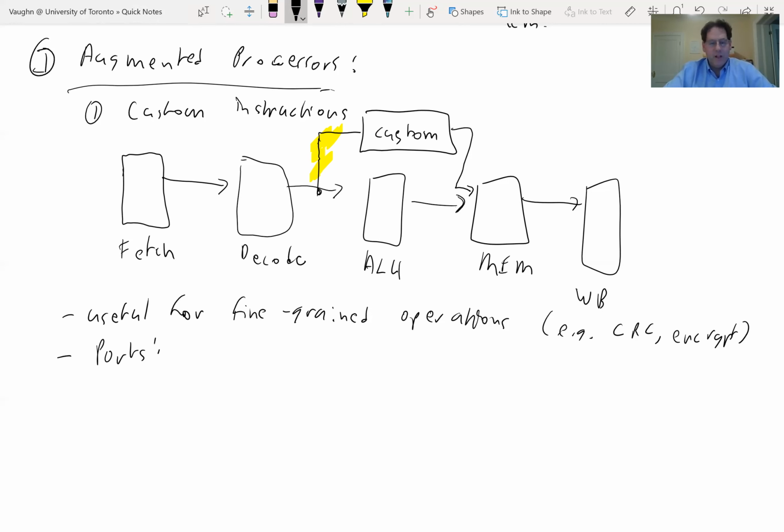The register file is centralized storage. It gets expensive to add many ports. And an ALU normally only reads two operands, so it doesn't need that many ports. If our custom instruction needs some huge number of ports, it just doesn't fit into the processor pipeline. We only built a very limited number of register ports, probably 2 read ports and 1 write port for the simple processor that I've shown here. Okay, so our ports are limited by the register file.